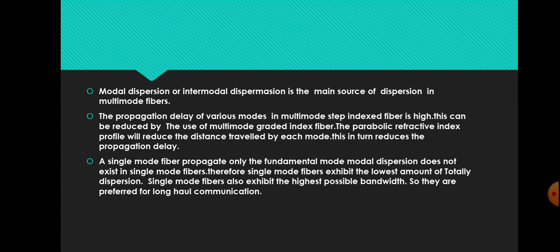Therefore single mode fibers exhibit the lowest amount of total dispersion. So single mode fibers also exhibit the highest possible bandwidth, so they are preferred for long haul communication. When we calculate the total dispersion, single mode fiber exhibits a lesser amount of dispersion compared to multimode fibers, because in single mode fiber there is no intermodal dispersion. That is why it is preferred for long haul communication.